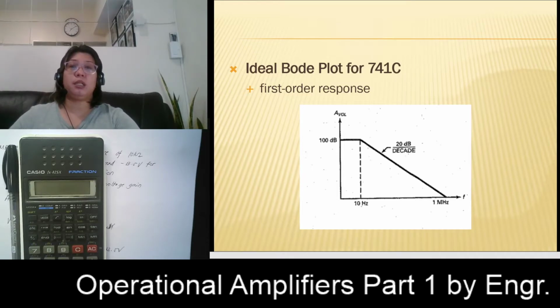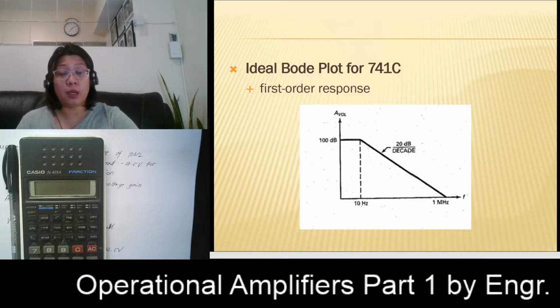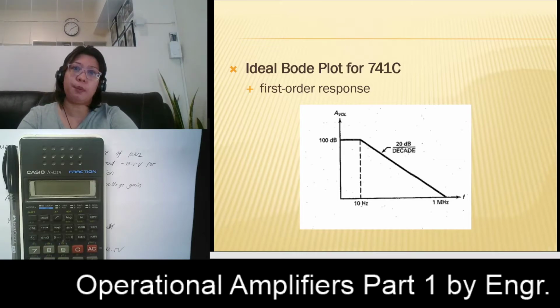Since operational amplifiers do not use coupling capacitors, or transformers at the input side, and since it's a differential amplifier, it starts at zero hertz. It starts with zero frequency.